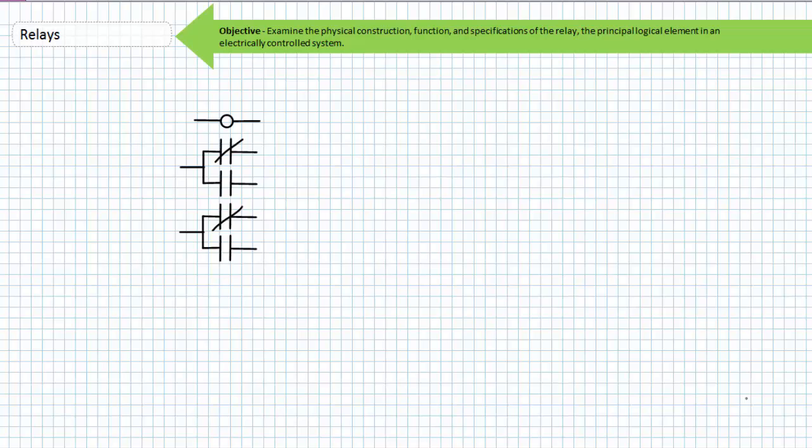Relays are part of the control aspect of a system. You should understand that when the coil of a relay is energized, the associated contacts change to their opposite state. As we'll learn in later lectures, the associated contacts, although physically part of the same relay, can be electrically all over the map. The coil for control relay 1 could be in the second rung of a ladder logic diagram, and the first set of associated contacts could be in the 7th rung, while the second set of associated contacts could be in the 15th rung.